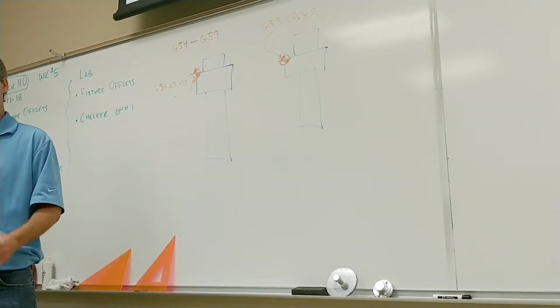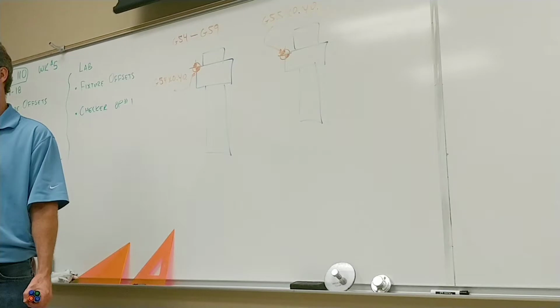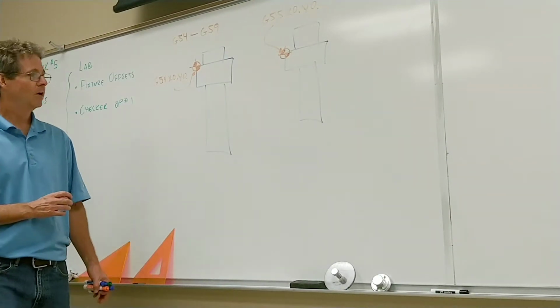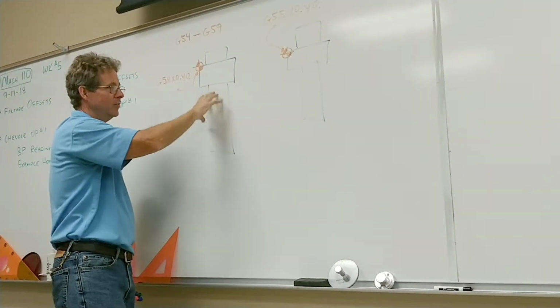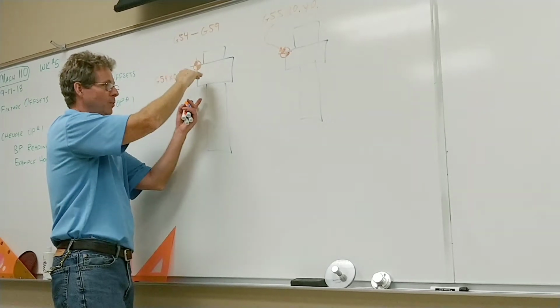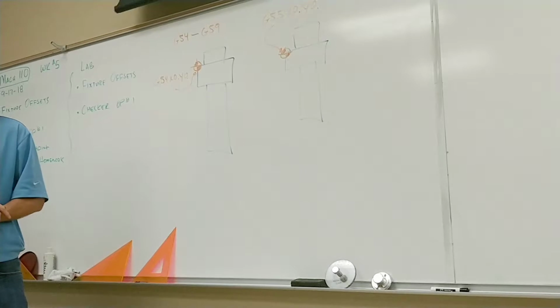Okay, it's common for a 2-inch piece of extruded aluminum, the tolerance is like plus and minus 20 thousandths. It's a pretty good tolerance. Okay, so what will happen is, if you set up on one part and your origin's on this side, and this is your movable jaw, you're going to put another part in, and your whole part's going to float because of it. Your dimensions and what gets machined on it are going to change.